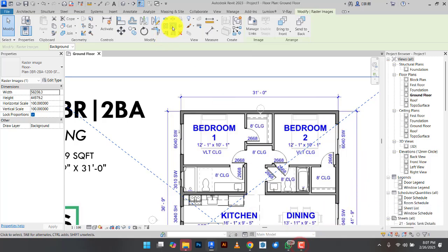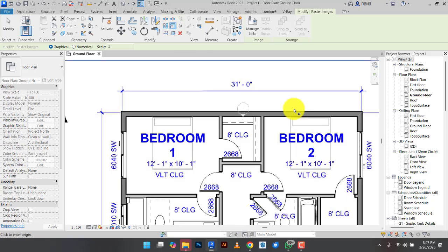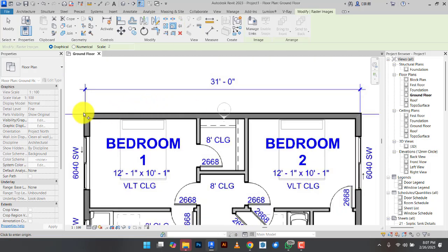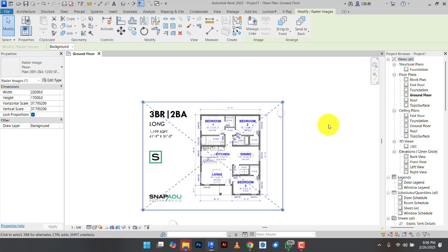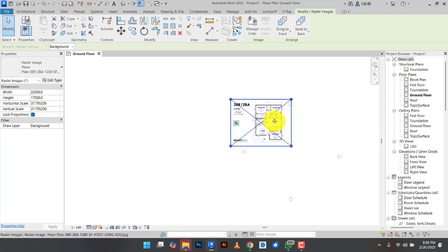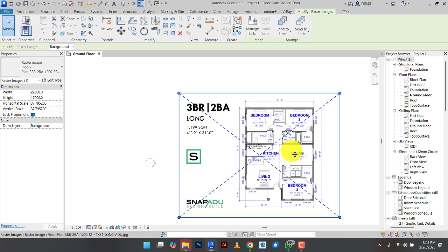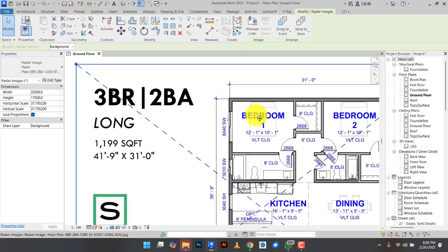So click on scale and zoom in and click on the end here and move and click on the end here. After clicking, you type 31 FT. That's 31 feet. Then press enter. Then to scale the drawing, either down or up, depending on the drawing. So this one I scaled down, as it became smaller. So it means that now it's scaled proportionally. So if I draw a wall from here to here, it should give me 31.